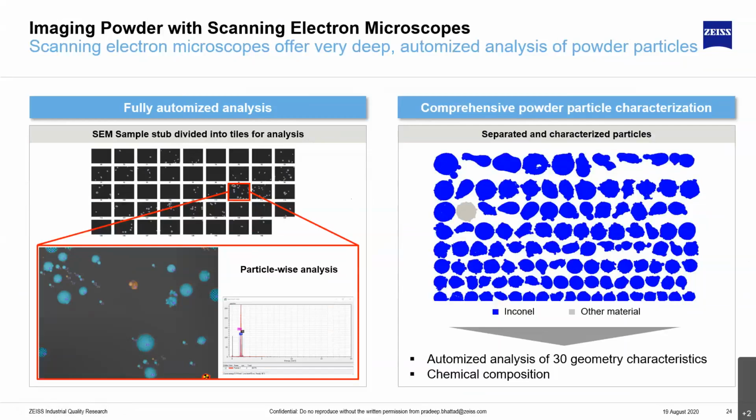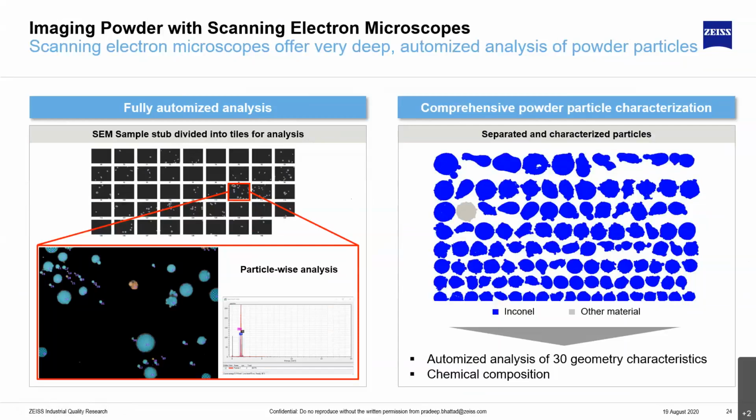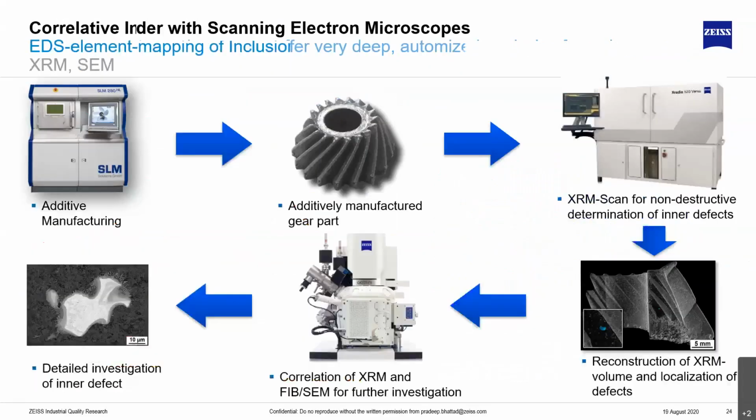Vice versa, if we have Inconel impurities or tungsten impurities coming into your lower melting material, then those particles might just remain as an inclusion in your final part. And that can often be the crack initiation sites in your final part. So we have an example where we saw, in an Inconel turbine blade, we had tungsten powder, and that was a crack initiation site for those blades.